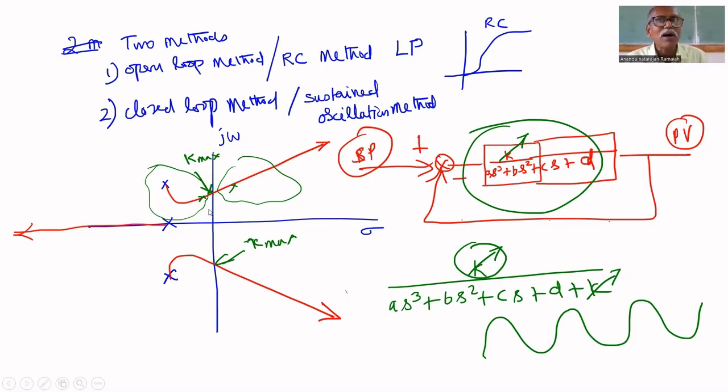Or the gain margin must be 2. Have you studied gain margin, phase margin? In control systems, this is the meaning. Gain margin 2 means, on a linear scale, you are 50% away from the unstable. If you multiply the gain by 2, it becomes unstable. That is the meaning. In the verge of instability, not unstable, it means always oscillation. So, we have to find that point.